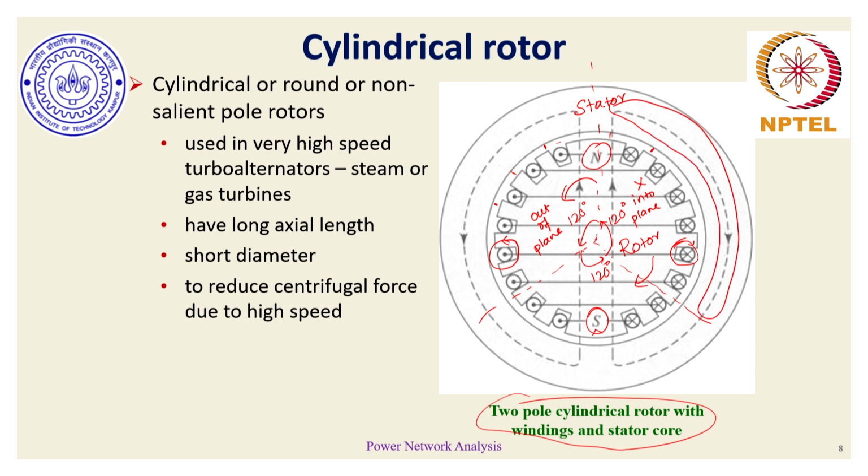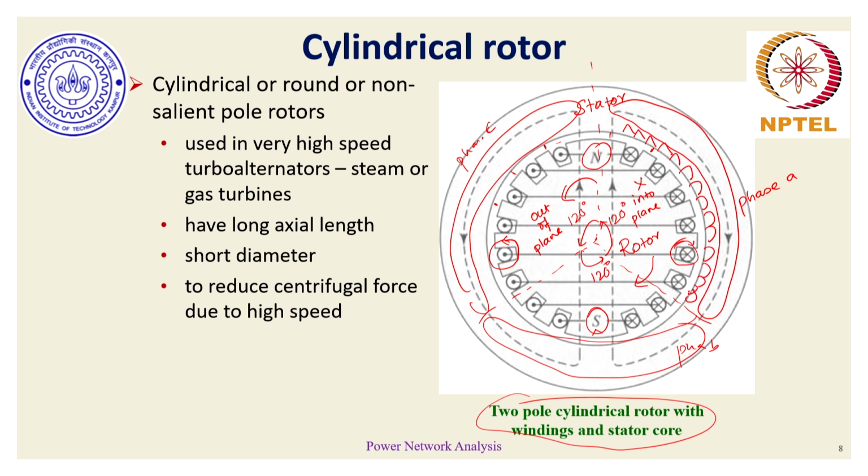then probably one half of this 120 degrees can correspond to phase A windings. The other half could probably correspond to phase B windings, and the third half may correspond to phase C windings. And on all these windings or slots, there are multiple slots present where there are different numbers of stator armature windings, and each of these armature windings may carry current, may not carry current, depending on whether the machine is electrically loaded or not. This is just a conventional notion of how the slots would look like on a stator.